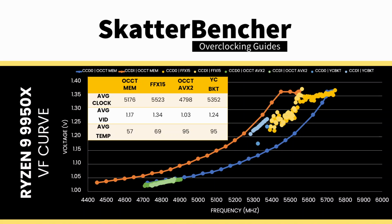I want to emphasize this point and refer to my Ryzen 9 9950X overclocking guide, where I demonstrated that the VF curve changes depending on the workload. With a dynamic voltage frequency scaling technology like Precision Boost 2, it's vital to test a wide variety of scenarios as opposed to just a heavy all-core workload pushing the power consumption to its limit. Sometimes your all-core AVX workload can be entirely stable, but you get blue screens in games.